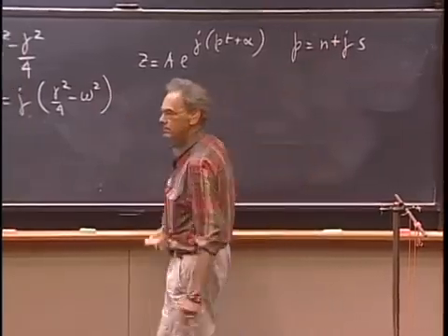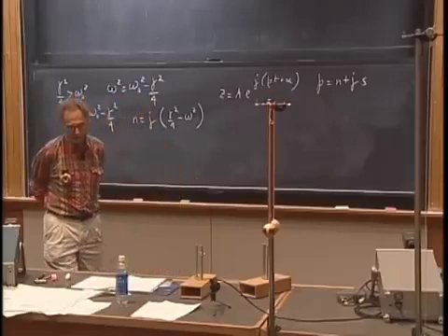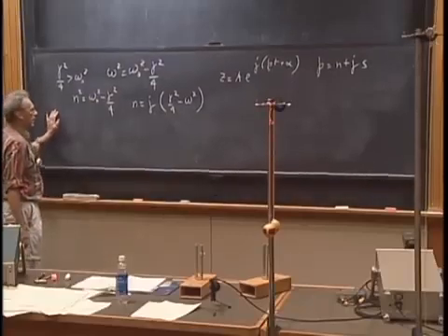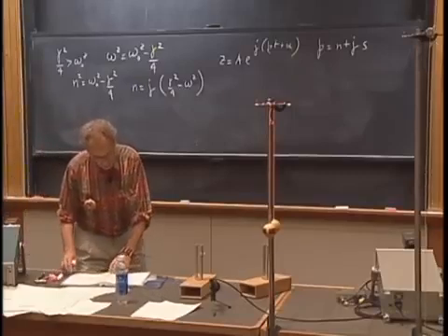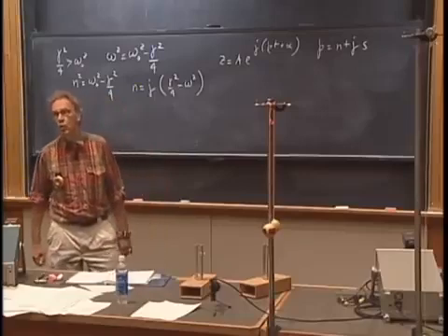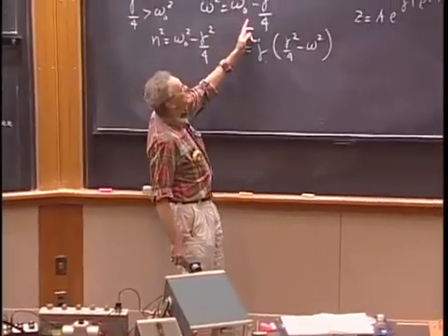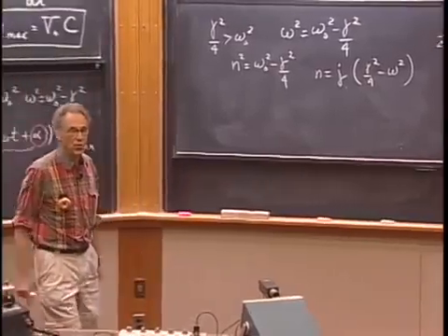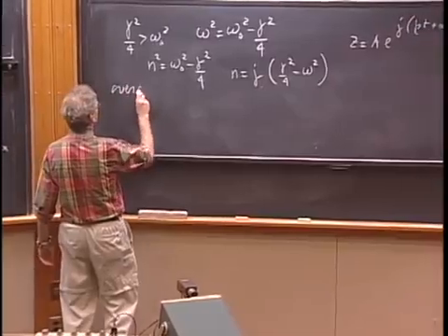If you do that now, and you turn the crank, then you get the valid solution for z, and you take the real part, and you get the valid solution for x. And I will write it down immediately in terms of x. And the outcome is very surprising. We call this an overdamped system, whereas a system whereby this is positive is an underdamped system. So the examples that I've shown you are underdamped systems, and this is overdamped.